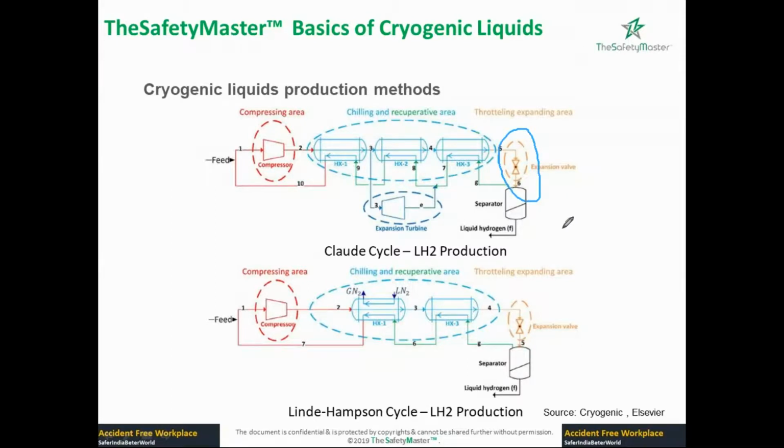As per ASME Section 8 you will design the pressure vessel, but you should take into consideration that the material has to be for cryogenic application. The thickness calculation will be based on ASME Section 8.